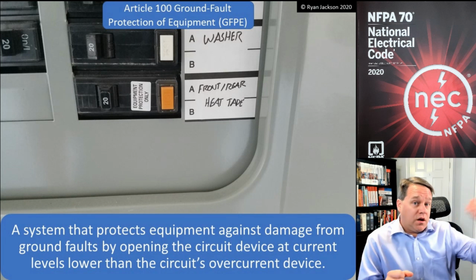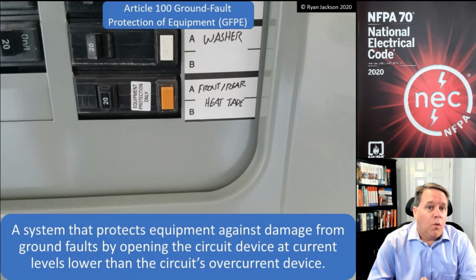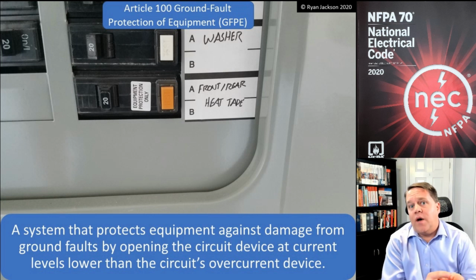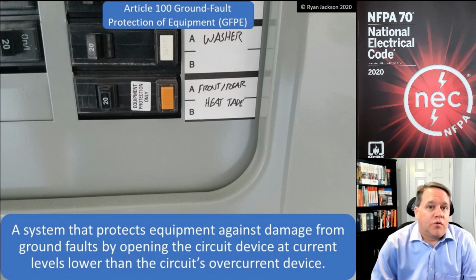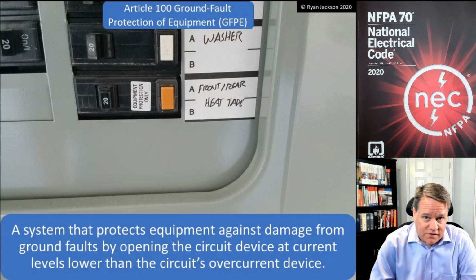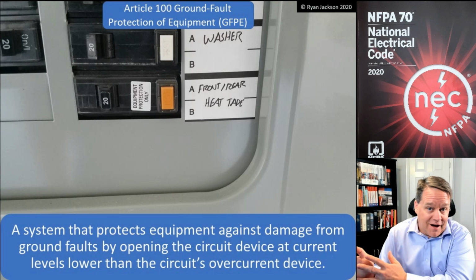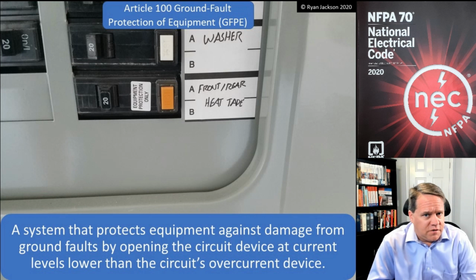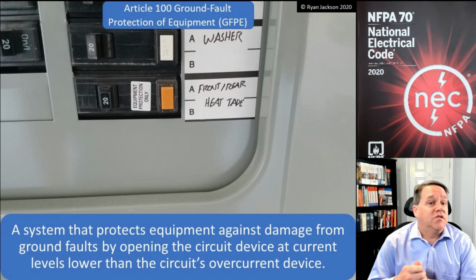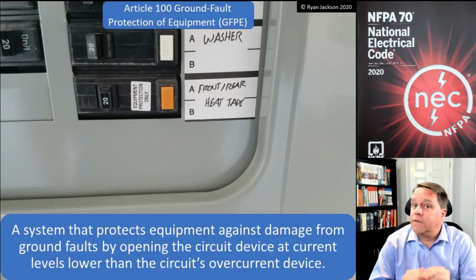And when you get into bigger systems, and by bigger systems, I mean three-phase, solidly grounded, Y-connected, 277, 480 volt systems, once you get into those systems and you have a 1,000 amp or greater overcurrent device, that main has to have ground fault protection. And it certainly is not set at 30 milliamps. It's set at like 1,000 amps, or it can be set significantly higher than 30 milliamps. So don't think that that's a standard. Ground fault protection of equipment does not protect people. It protects equipment. You cannot use ground fault protection of equipment as a substitute for GFCI.